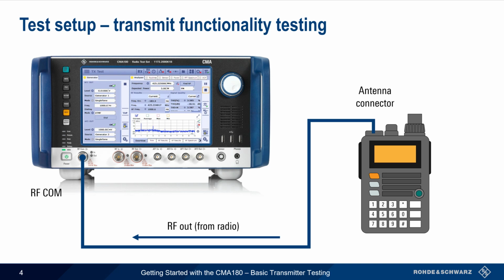This can be done in several ways, the simplest of which is pressing the radio's PTT or push-to-talk switch. Many radios also have a way to connect an external PTT switch to activate PTT. And finally, some radios can also be configured to transmit when audio is received. This is often referred to as a VOX, or voice-activated transmission.